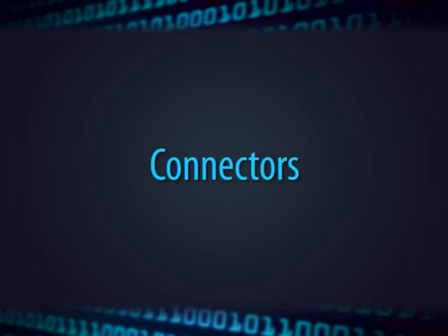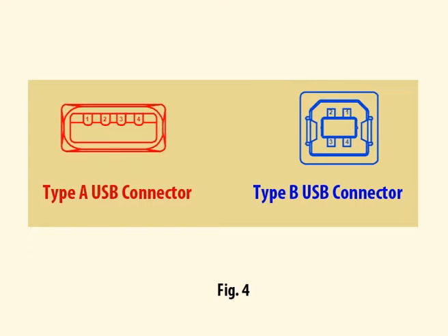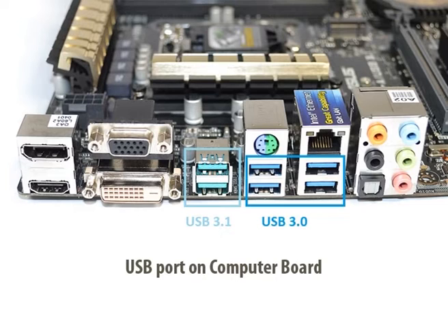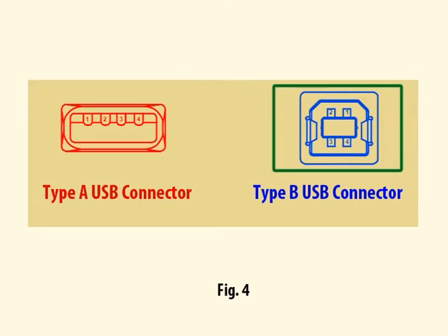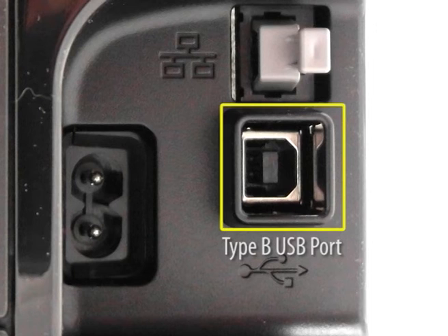In this section, we will discuss hardware, protocol and software details of USB. Connectors. All devices have an upstream connection to the host and all hosts have a downstream connection to the device. There are commonly two types of connectors called type A and type B, which are shown below in figure 4. Type A plugs always face upstream. Type A sockets will typically find themselves on host and hubs such as computer main boards and hubs. Type B plugs are always connected downstream and are found on devices such as printers.